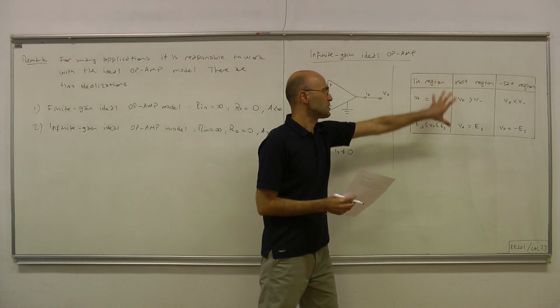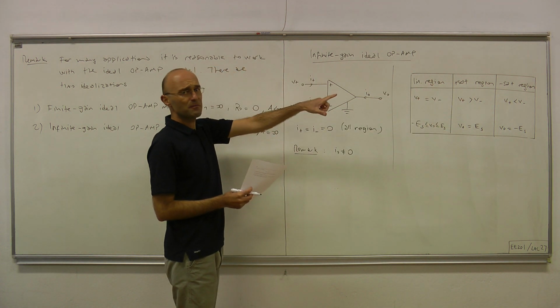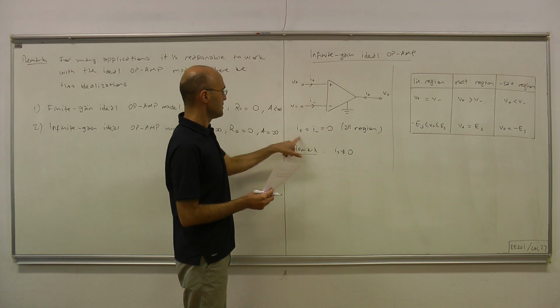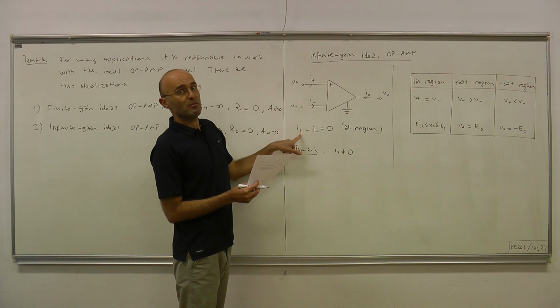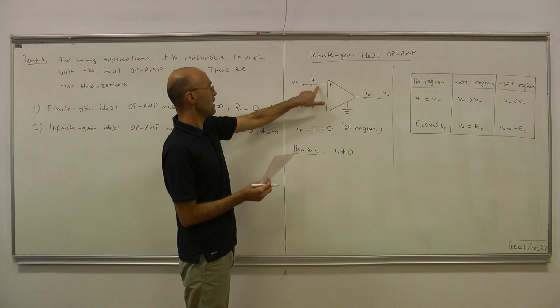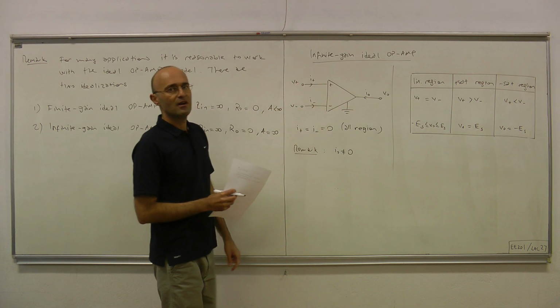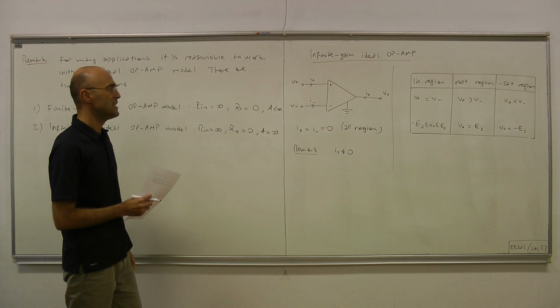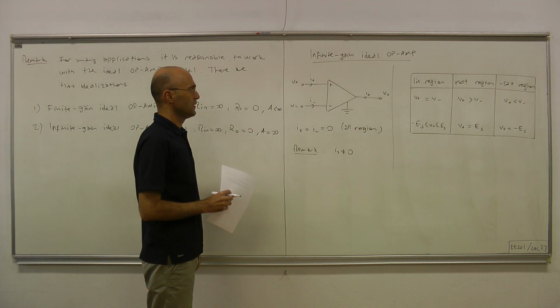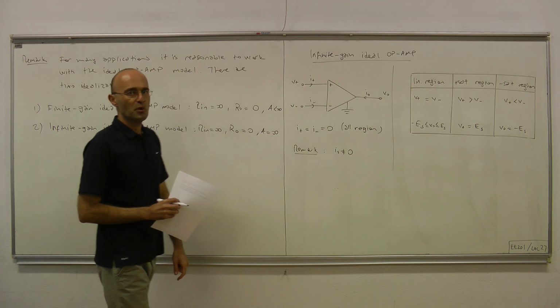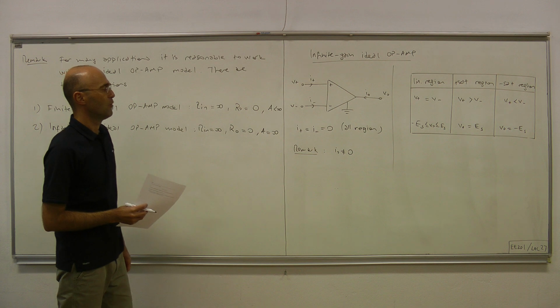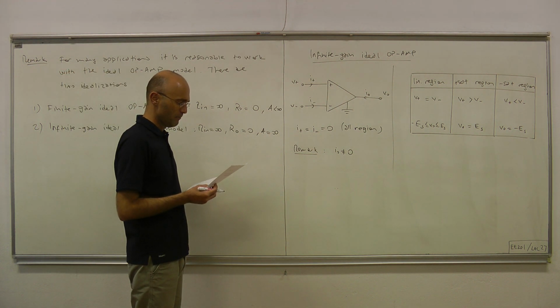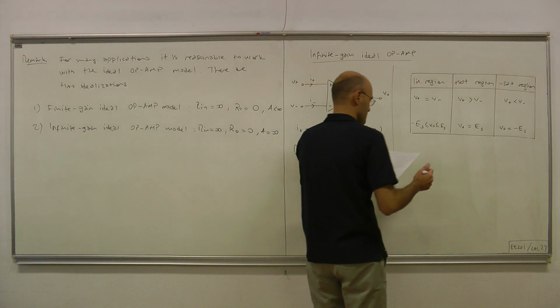This is part of the model. In all regions, I plus and I minus, these two currents, are zero, and that's all we need to be able to analyze circuits that have operational amplifiers in them.